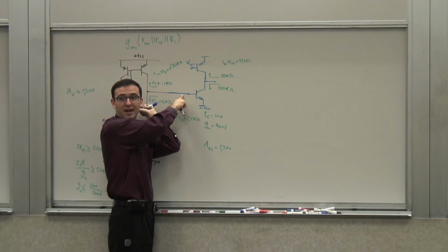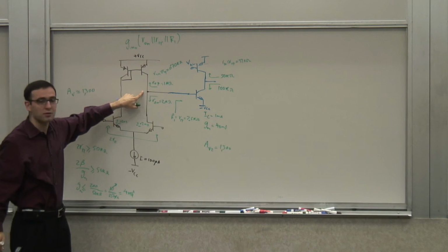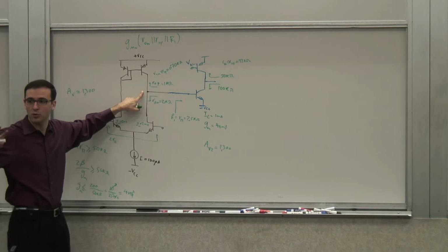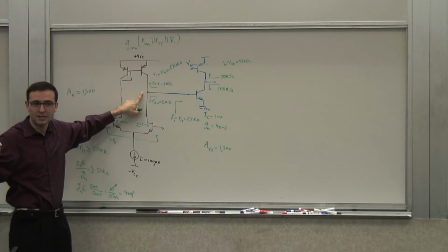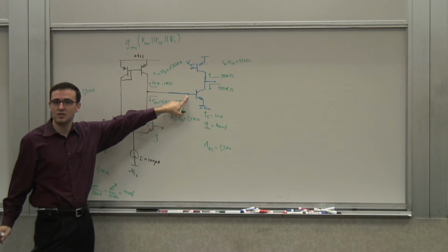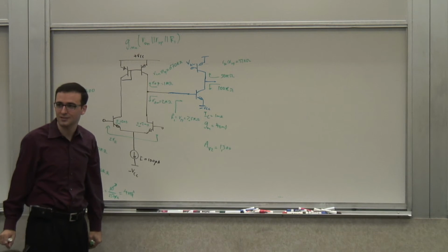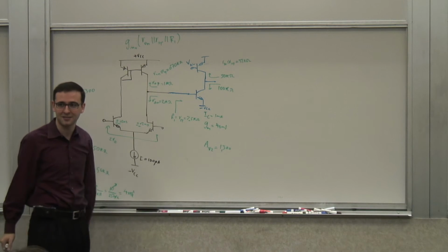VBE above minus VCC. So, if, let's say, VCC is 10 volts, this is probably 9.3 volts. I mean, this wants to be at 9.3 volts when it's happy. This wants to be at minus 9.3 volts. And they're far apart. So you see the problem right there. So how do I fix that? I mean, I'm talking about something like 18.6 volts difference that I have to maintain.